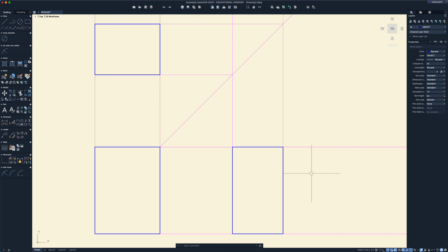Now, let's start to make some of the finer details in these. So on the front view, there is a ledge that's going right here, creating that shelf. Now, I'm just going to use the offset command. It's going up 226 millimeters. So O, enter, 226, enter.